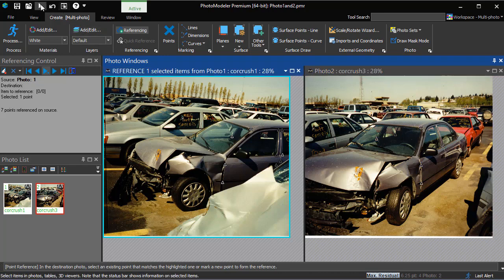If your project has large residuals and the projected imported model or reference helper line is not lining up, check your control point placement. You should also make sure that the exemplar vehicle that you got the control points from is the exact same model. It should be the same make, year, and model. Even some minor features such as body lines and molding can vary in shape or location in the same models due to dealer options and production variations.